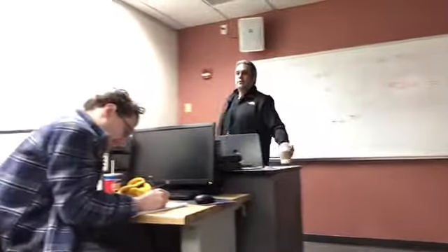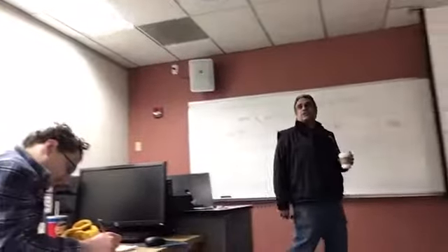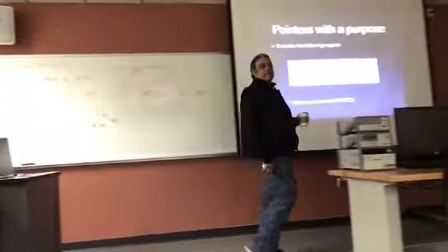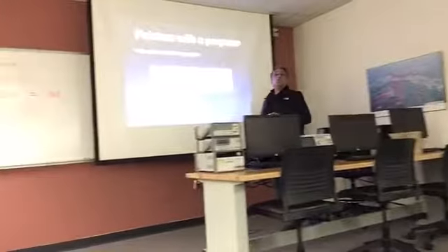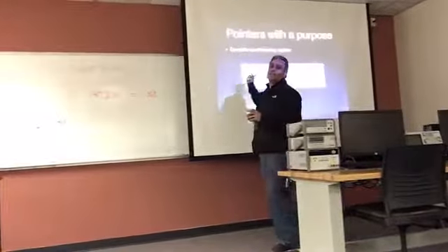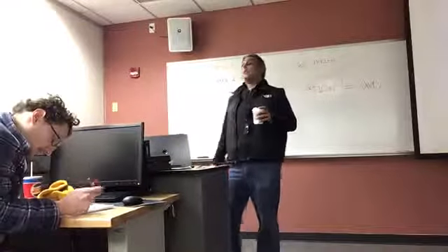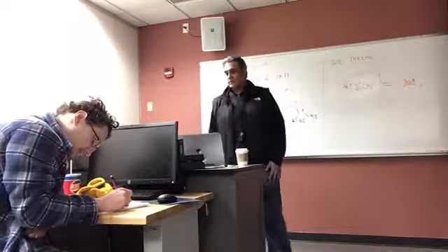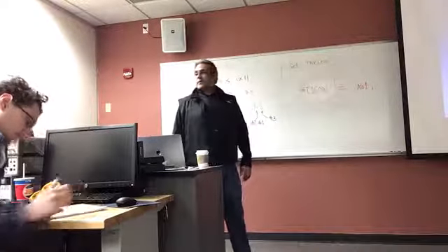Reset it. The circuit is called TMR1CS. It's called a clock select. It's selecting the source of your clock. That's what that does. I have a timer. Who's going to feed my timer? That's what that circuit does. We're going to study a little bit more about it later on. How do I put a 0 in it? Okay? Take a look at your little tables that you wrote. And let's stick a 0 on that spot.